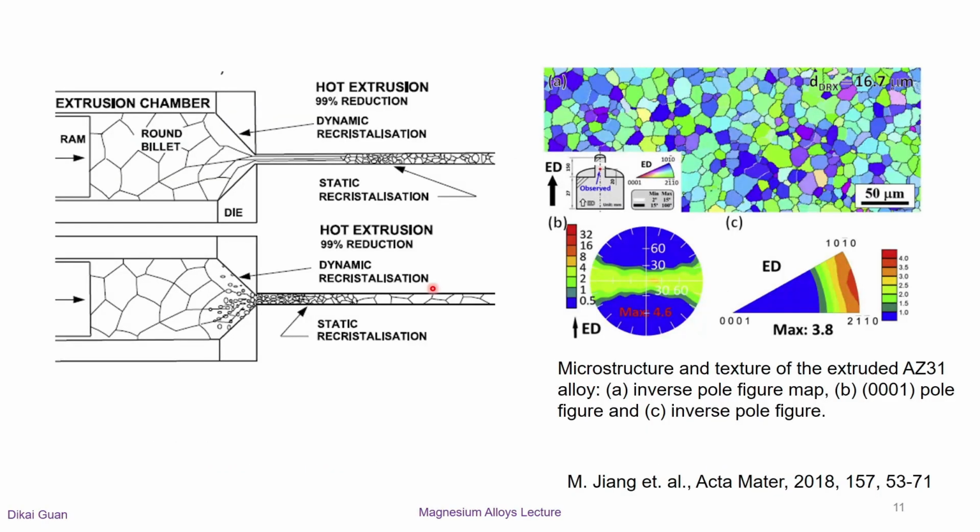Extrusion of magnesium alloys is a typical case of hot working practice, where a heated billet is deformed into the required shape at a rate determined by the process equipment. The strain rate time profile is usually defined by the process. Hot working operations such as extrusion are conducted in a high strain rate range of 10 to the power minus 3 to 10 to the power 3 per second and develop relatively high stresses.